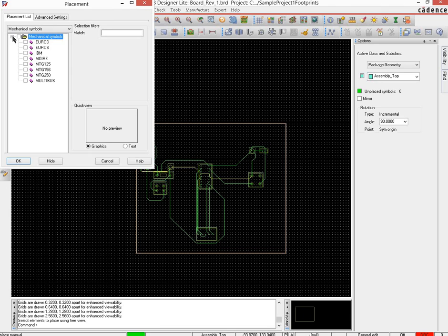You drop it down and you can choose any one of these 3 mounting holes which are there. Now a mounting hole with 125 mils diameter is good enough for the hex standoffs to go in, so we will use that. And then what we will do is we will place 4 of them on the board. So let us place it near the edges of the board. So let me place one here, then so that is there. And then what else?